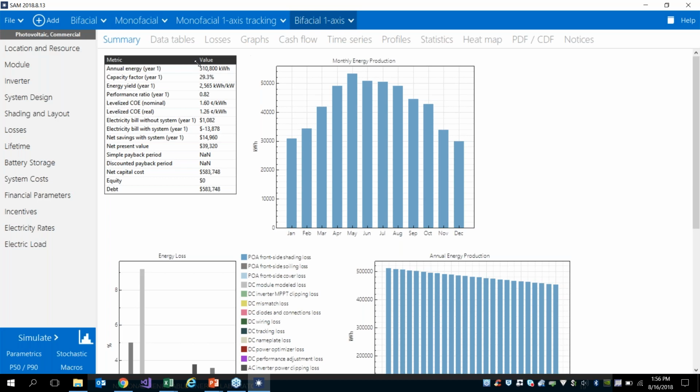So within a 4 kilometer by 4 kilometer grid cell, you are still going to experience a decent amount of variation in what the albedo is, depending on the exact surface that you're installing your system. If you are installing your system in a field, then your albedo is going to be different, even within that same 4 kilometer by 4 kilometer cell, than a building located there as well. So that would be the caution for that.